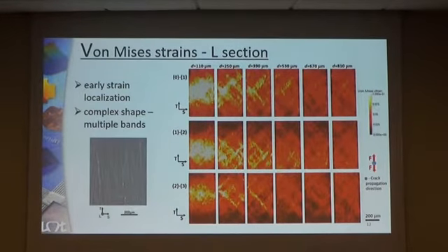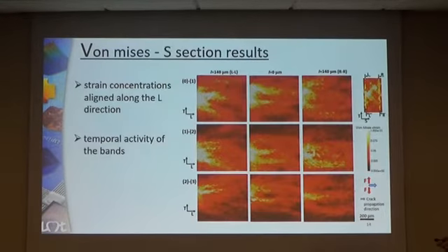While the grain structure reveals that the dimension of the grains in the thickness direction is between 10 to 30 microns, meaning that these reported slanted bands are spread over multiple grains. You can do the same thing, so plot von Mises strain maps for the 3 loading steps, but on the section that is normal to thickness direction.